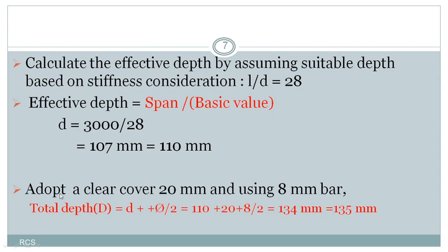Then adopt a clear cover of 20 mm and using 8 mm bars. By using this condition, I am calculating the overall depth. After knowing the effective depth, we can easily calculate the overall depth.